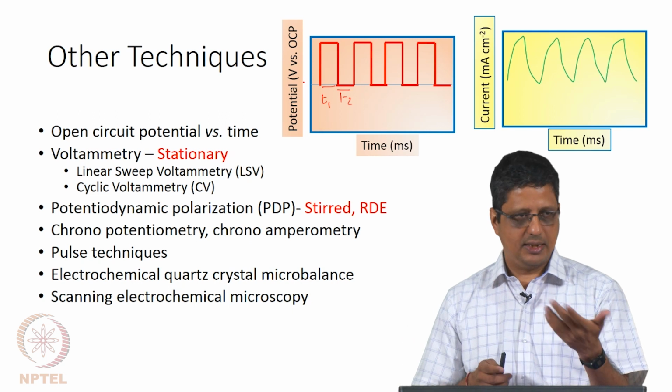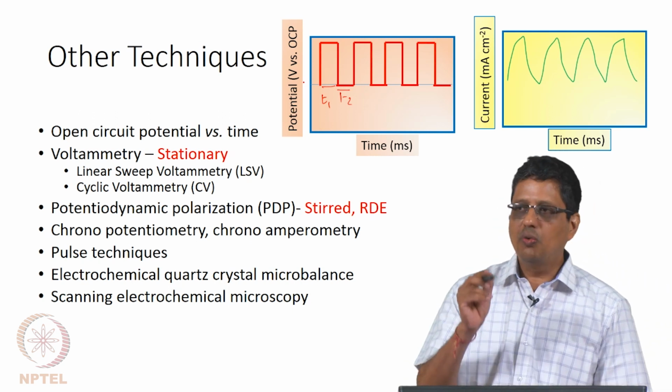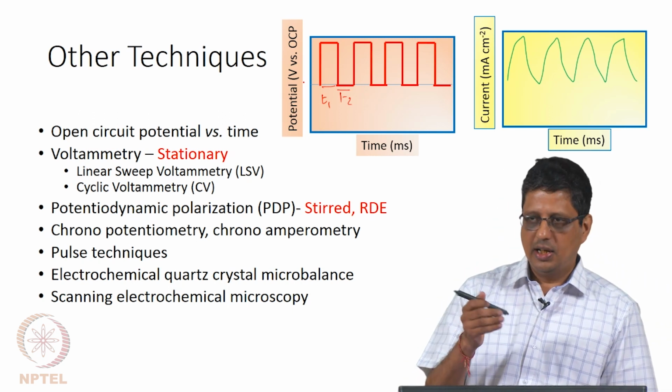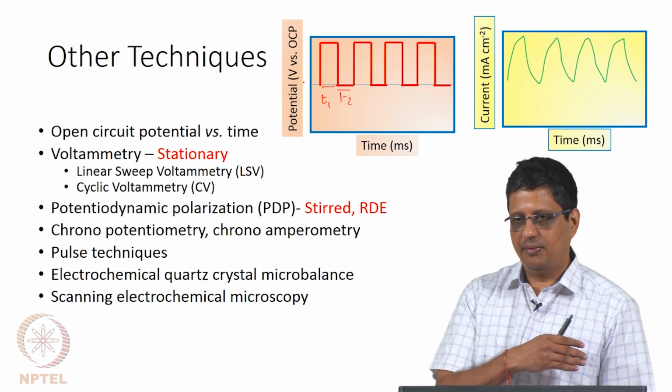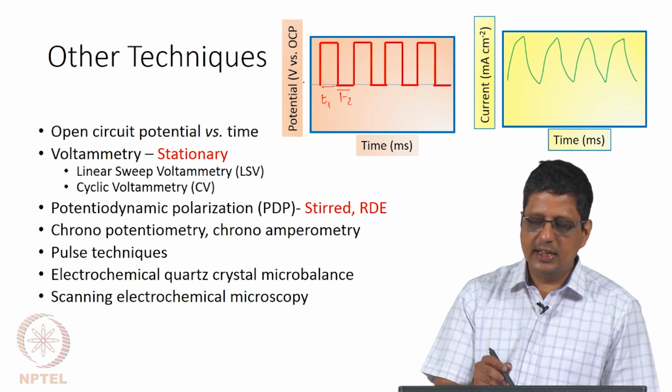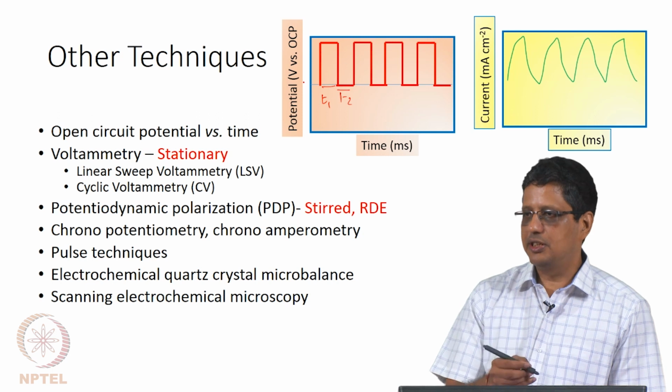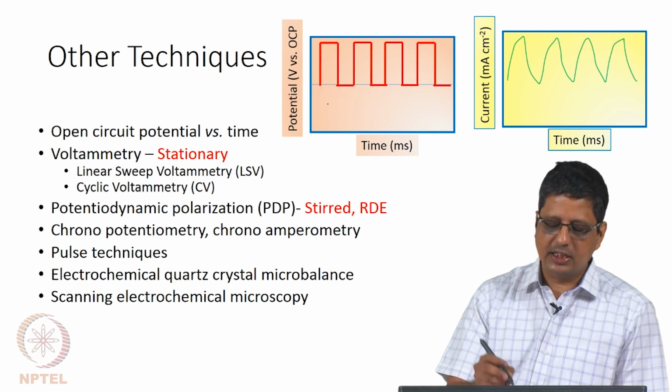Of course, you will have to optimize this by trial. You do not want to give a large and long reverse pulse, because you are going to remove everything, but occasionally it is beneficial to give a reverse pulse also. Occasionally meaning in some systems it is beneficial.